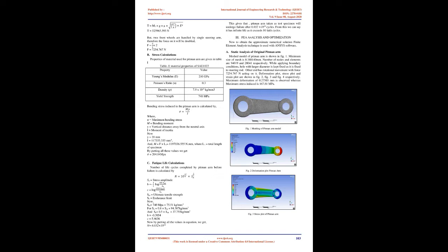A new material, austempered ductile iron, was proposed for the Pitman Arm. The strength of the Pitman Arm was found to be increased with the new material. 6. The new material showed a homogeneous microstructure, was less prone to failure during deformation, and increased the elongation of the original material, making it more deformable. All the above studies indicate the scope for optimization of the Pitman Arm.